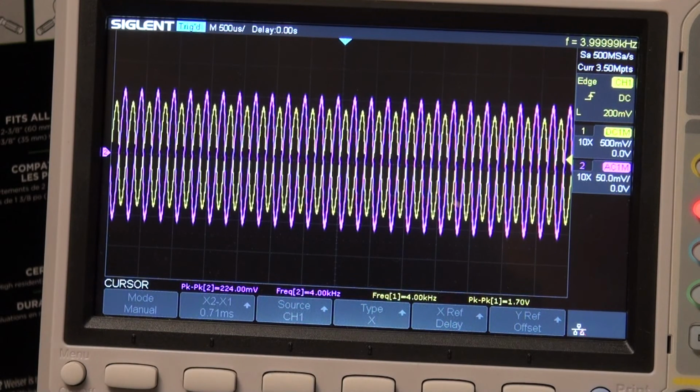So I'll just do it in the calculator. Take the ratio, 1.7 divided by 0.2. So that's a gain of 8.5. So it's from 30 to 8.5. It's dropping. It's suppressing, it's knocking down the gain as the signal level is rising, just as we would like it to do.